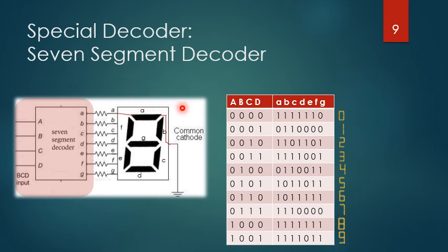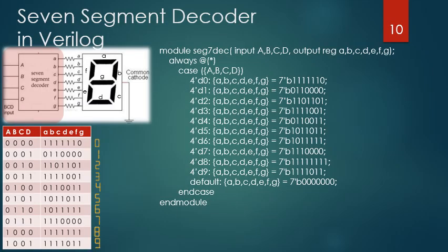This is under the structure or connection that we call the common cathode, where all 7 segments connect to a common node, which is the ground. That's why we call it common cathode. So for a common cathode 7-segment display, to turn on you need a logic 1. You may also find the common anode type of 7-segment display.